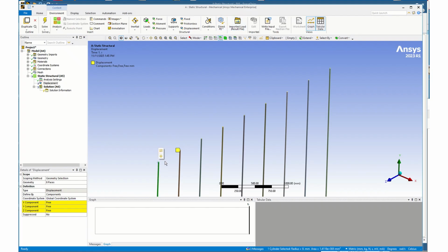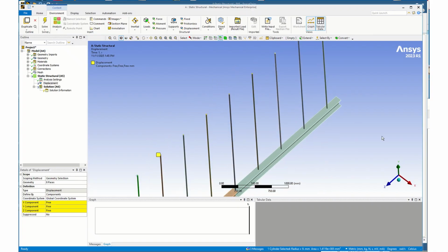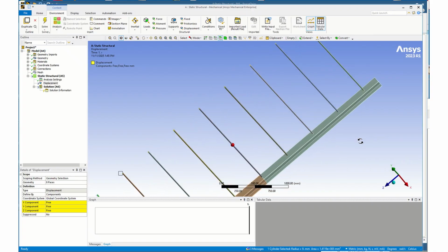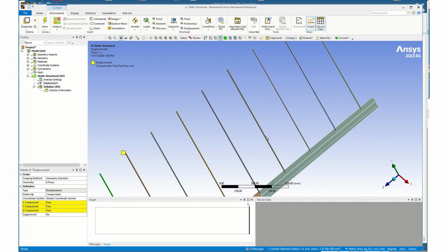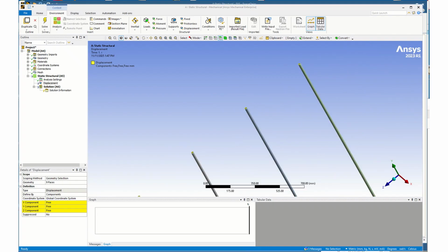The thing you've got to be careful with is that oftentimes, like I just did, you'll select the face of the circular rod, and that's not the face that you want to get. So I'm going to start over and grab those top faces. Having done that, you can now see that I have 9 faces here.